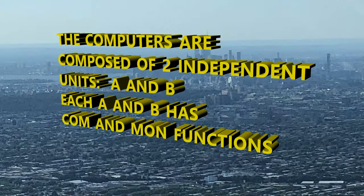Each of those units has channels, or functions: a command and a monitoring function, for each unit. So there are 4 total functions, 2 command and 2 mon, because there's an A and B unit for each primary computer and each secondary computer.